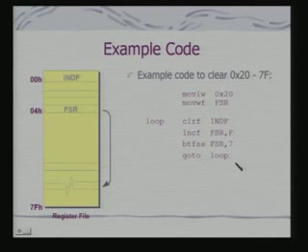And then we are going through this loop. Now, the interesting feature you should note here is how the clearing is actually taking place. We want to clear the locations from this to this. And how will this take place? It will take place because I am clearing INDF. INDF is an indirect addressing register. That means, when I am trying to clear INDF, it essentially means that the register memory location pointed to by FSR should get cleared.